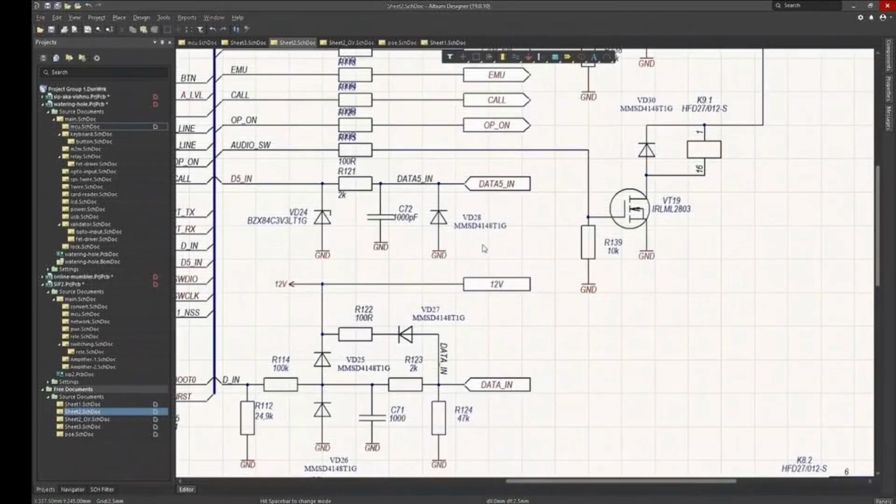The sixth mistake is not understanding the purpose of protective elements. Beginners often ignore the installation of protection diodes and protective resistors, TVS, because everything works without them anyway. Yes, at the initial stage, the board works normally, but then during debugging, the microcontroller suddenly stops responding on one of the interfaces.